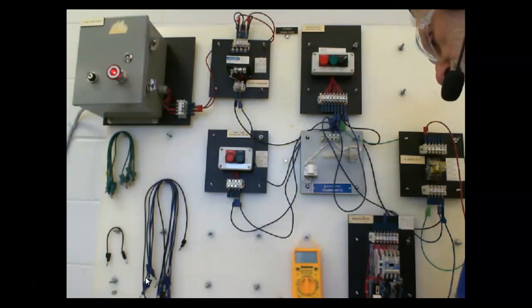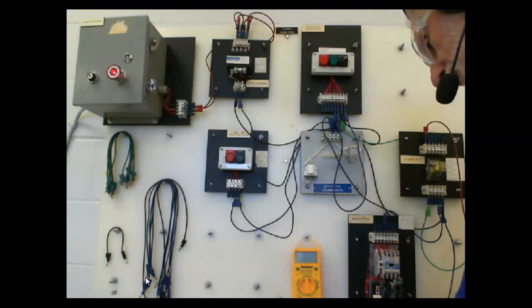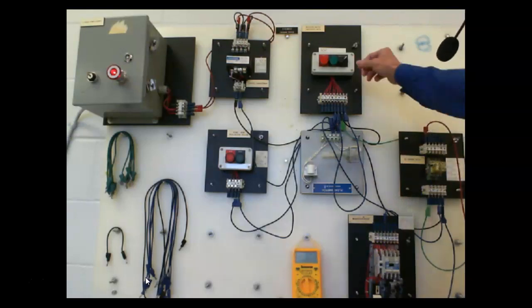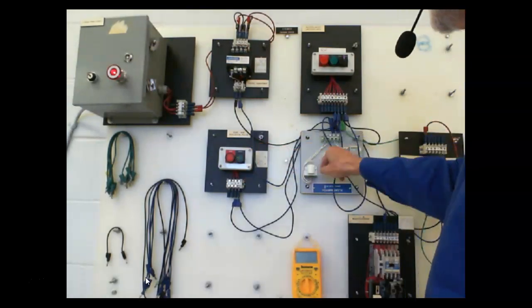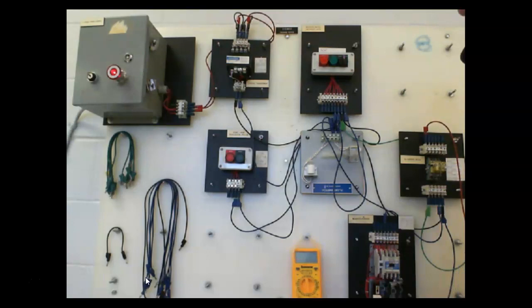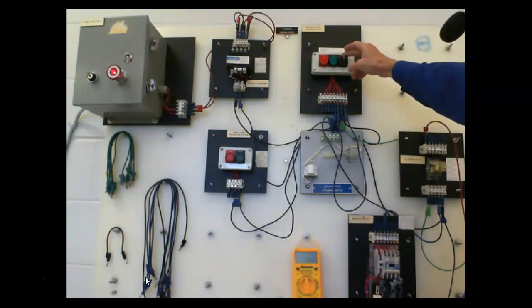Redraw the circuit, number 6, adding a red lamp in the on selector switch. Also add a green lamp on anytime the selector switch is in the auto position. No lamp should be on when the selector switch is off. Okay, so we've got the center position. In the center position, the whole system is off. So on this one, we wouldn't need that master start stop. All I can do is just turn the whole system off with my selector switch.